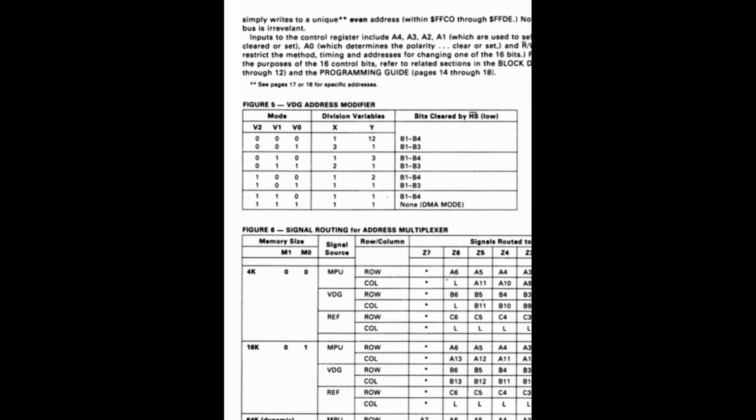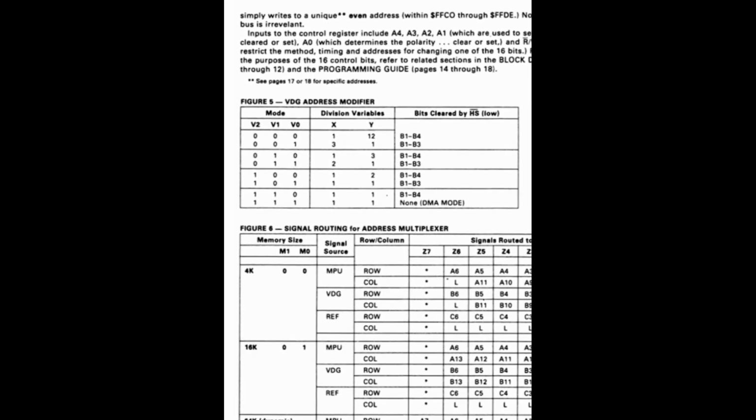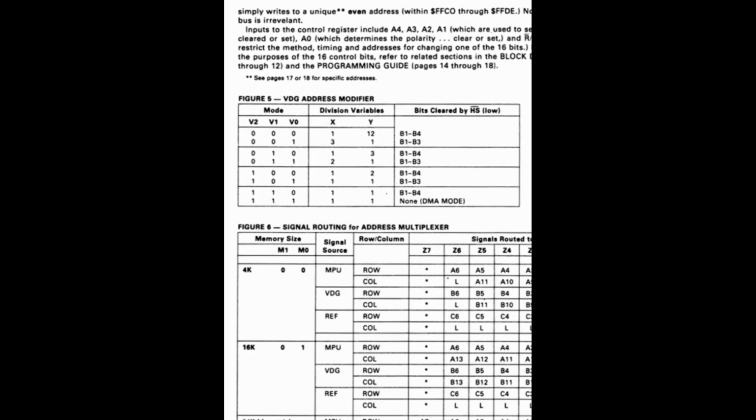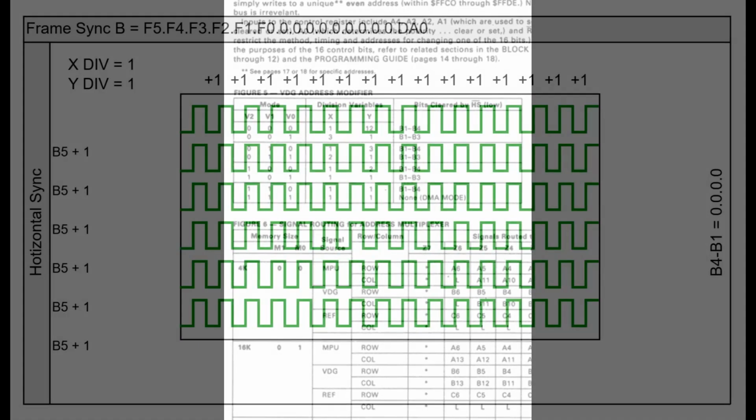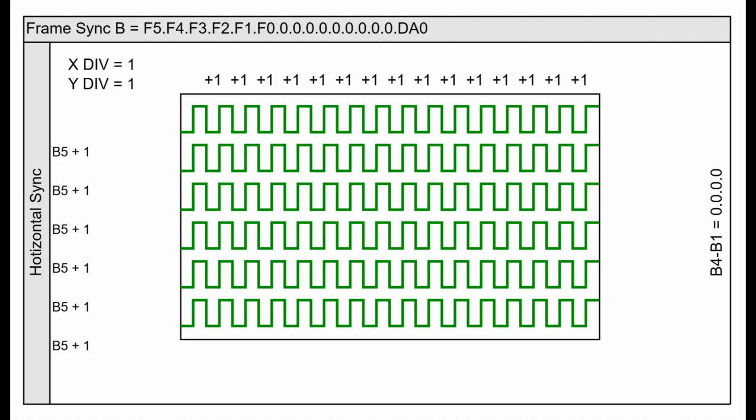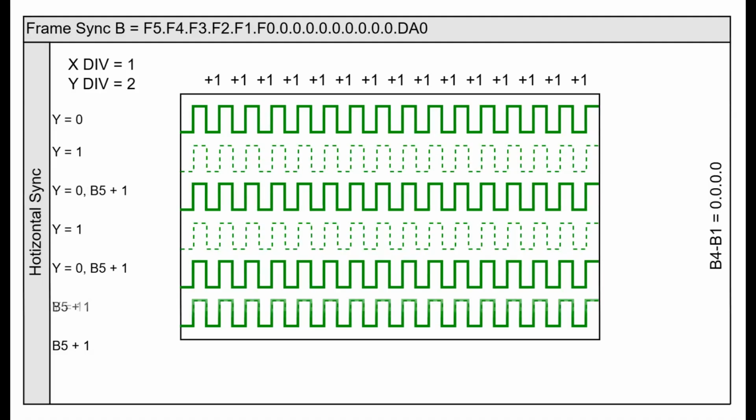The dividers, in combination with the video mode register, define how many bits of the video address register are reset on a horizontal sync when repeating a row. Whenever a vertical sync is received, the video address is reset to the base address. The horizontal sync always clears a number of bits from the video address register regardless of repeat, unless video addressing is set to DMA mode.